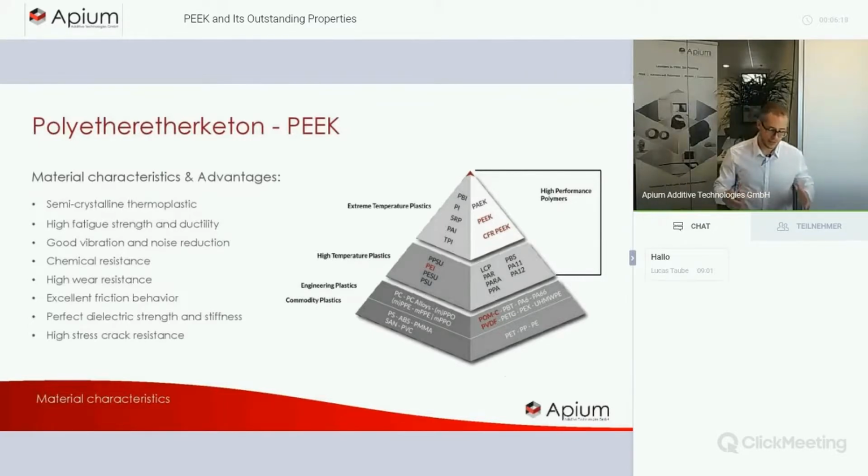So due to the amorphous part that is still in the polymer, we have a lot of energy damping opportunities. We also have the chemical resistance of the material, so it is resistant against most of the acids and bases. For halogenic acids, we see that this material is not resistant. Also for sulfuric acid, this material will get damaged.